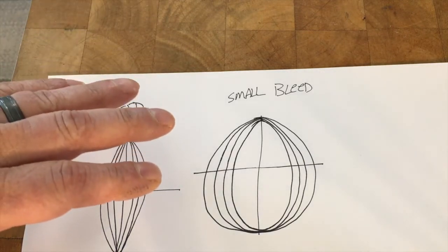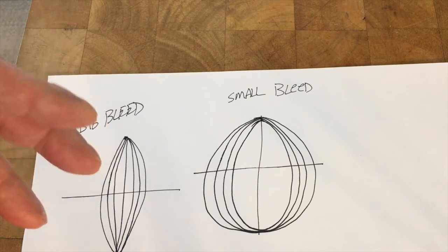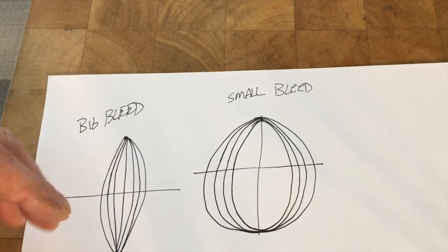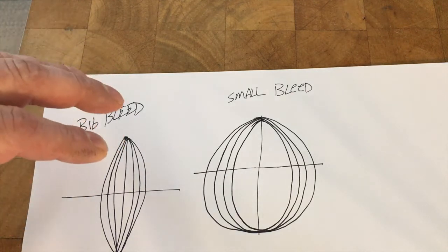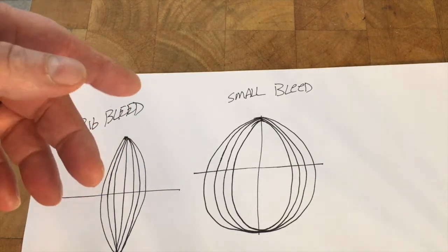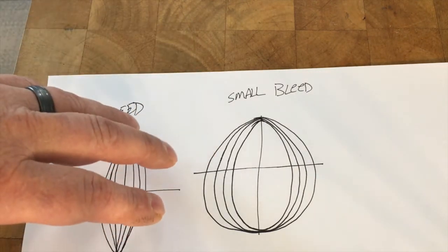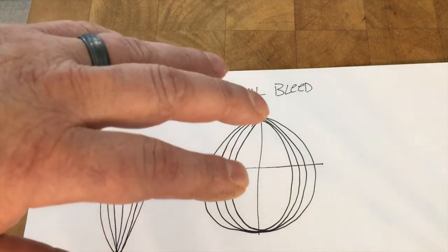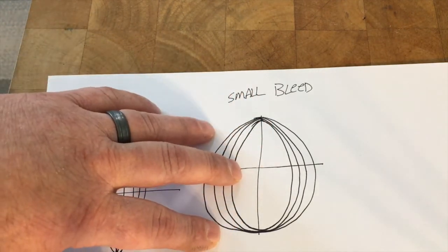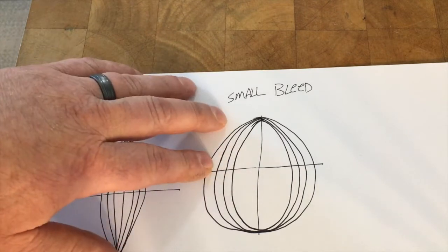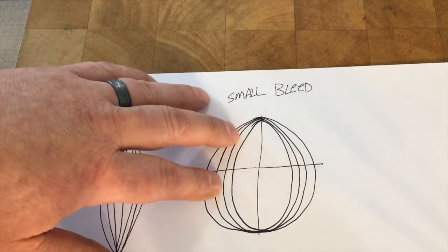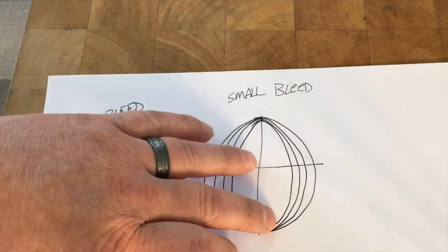Bleed is real interesting, and it's a real big tuning device in shocks. It's one of the largest, because your shock shaft, you think about it, 2 times every cycle, the shock shaft is going to come to a complete stop and then try to switch directions. It'll spend a lot of time at that 0 range.